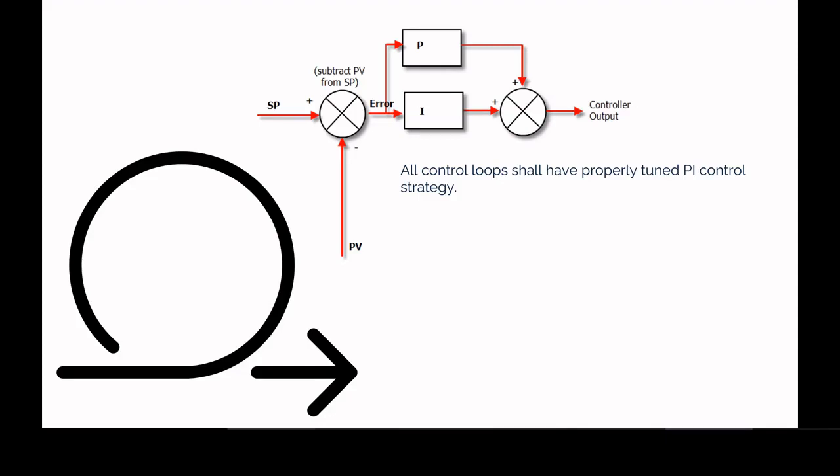So we have something called proportional and another thing called integral. The proportional element is really just to say, well, for every degree I'm out, add X amount to the output in order to try and get there. The problem with that is the moment you reach your set point, your output is at zero, and that's not great because you're never really going to hit your set point.